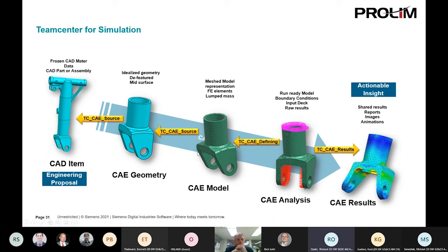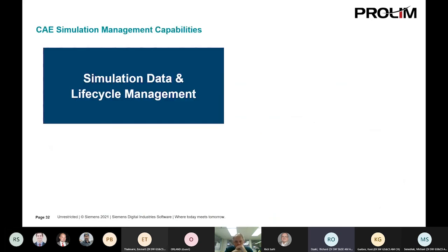Then we mesh that, so again, we're moving from a CAD geometry to a FEM model. They're still connected, but they are separate files. Then we add the loads and the constraints, and then finally we have the CAE results. So just here we have 5 different files that we need to deal with and keep track of, and if there's any revision control to be done, historically that's been done manually.